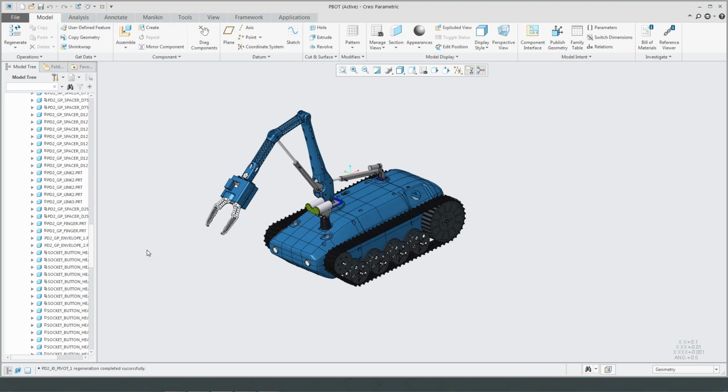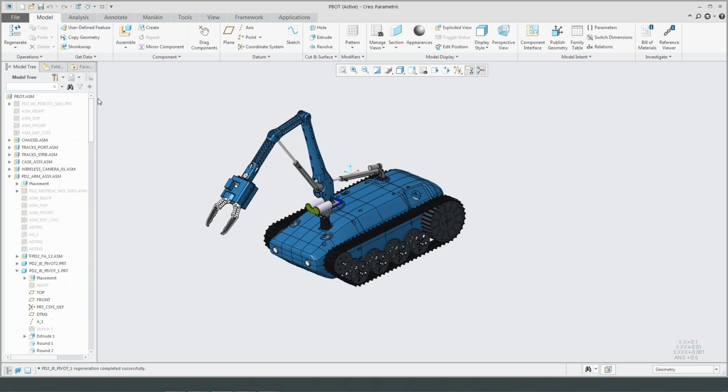So in Creo 4, we focused our efforts on embedding that with sheet metal. Sheet metal reacts a little differently. You always need to maintain a constant thickness. So it took a little longer, but we now have the ability to use flexible modeling in sheet metal. Let me show you an example of that.